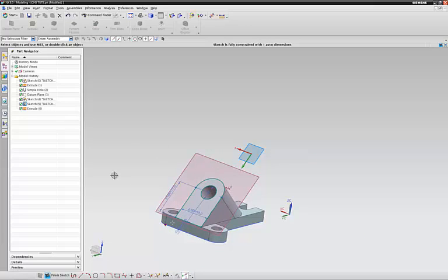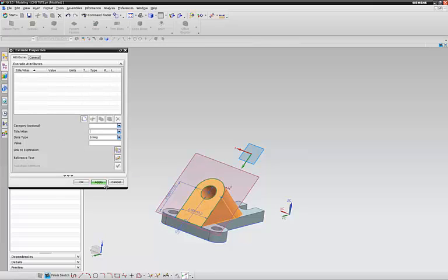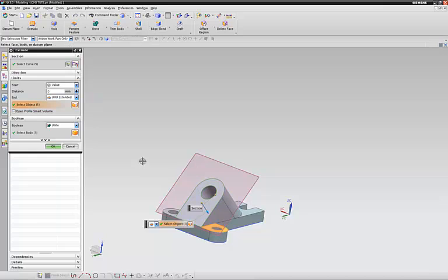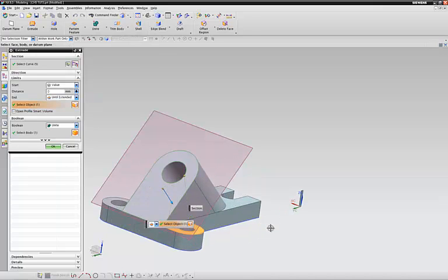Then once we had the sketch done, we wanted to extrude it. So on the extrude, instead of just going straight through and then cutting it back out later, which can work in some instances but will not work all the time, we wanted a value, distance didn't matter.